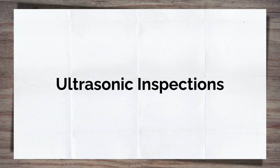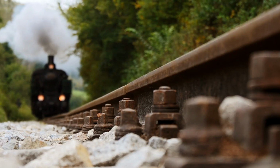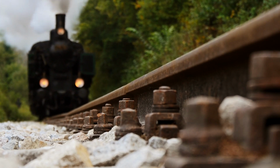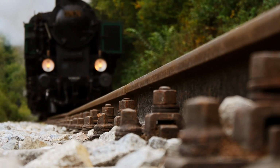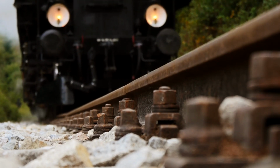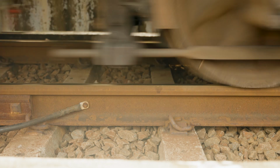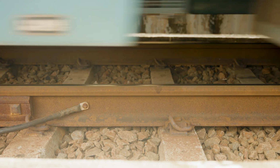Ultrasonic inspection. The rails are the key interface between track and train. They are subject to the concentrated load from each train wheel. This load causes various stresses and strains within the rail material, leading to wear and damage. This damage could be visible and picked up on the basic visual inspection, but more often than not it's too small to see, or maybe inside the rail itself. This is where ultrasonic inspection comes in.